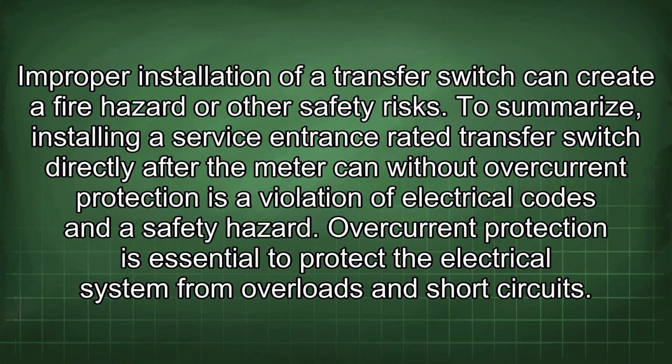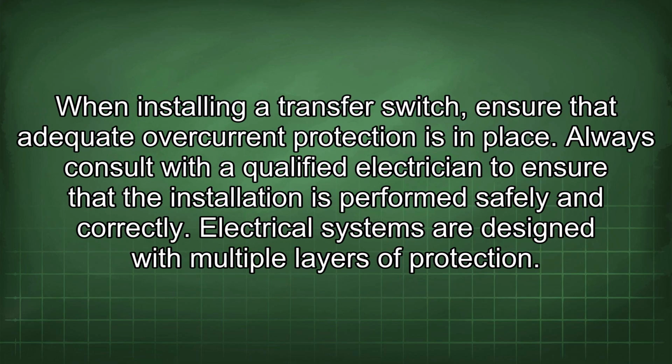To summarize, installing a service entrance rated transfer switch directly after the meter can without overcurrent protection is a violation of electrical codes and a safety hazard. Overcurrent protection is essential to protect the electrical system from overloads and short circuits. When installing a transfer switch, ensure that adequate overcurrent protection is in place. Always consult with a qualified electrician to ensure that the installation is performed safely and correctly.